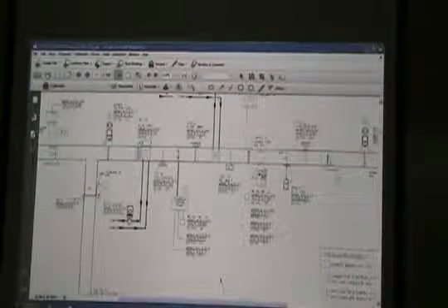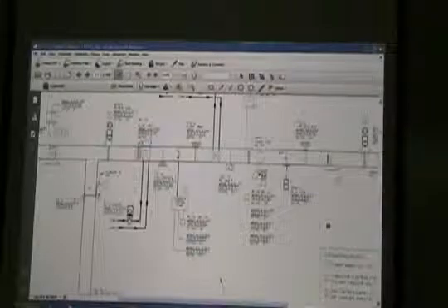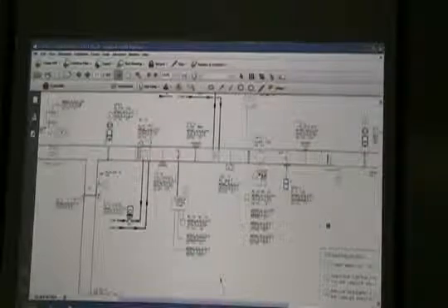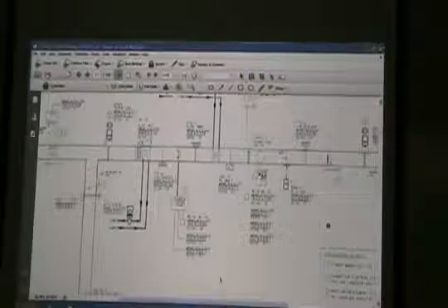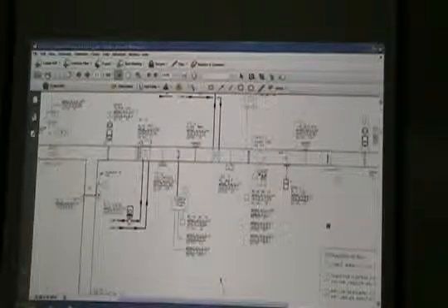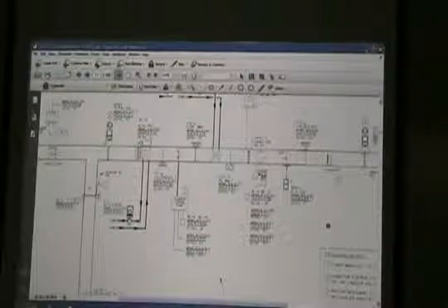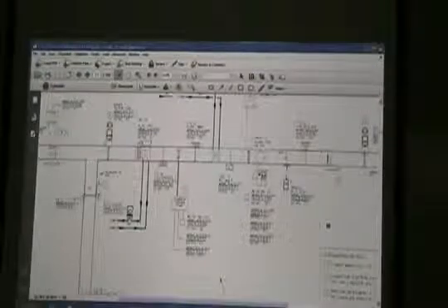And do we have any final filters? We got final filter right here. So this is like a 30% filter, and that's going to be like a 90% filter. We got a differential pressure switch on that, monitoring that filter. And all it does is tell the guy back at the front end, I need to go change my filters.